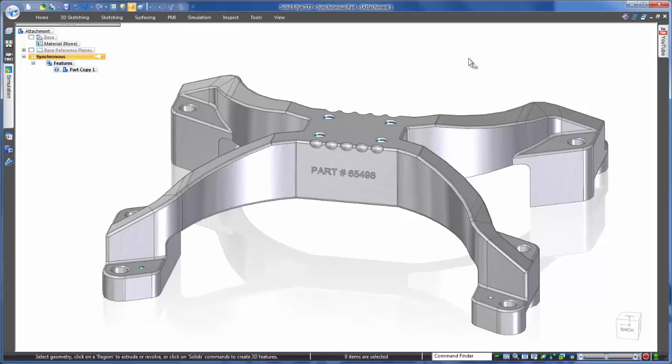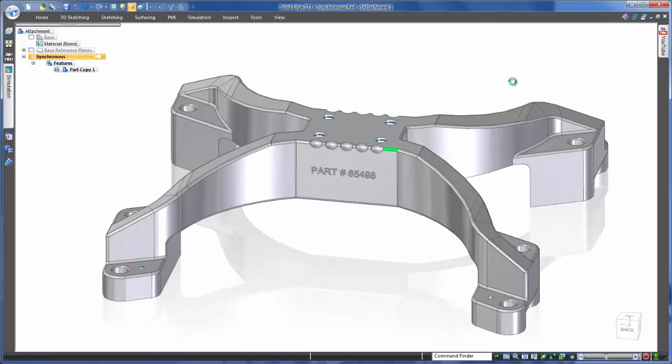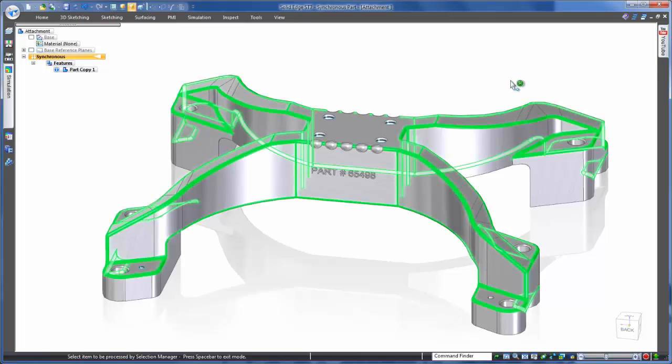Small faces can cause errors or long processing time, so it's always a good idea to remove these types of geometries if they don't greatly affect the structure. Unlike most other CAD systems, Solid Edge with Synchronous Technology doesn't rely on a delicate history tree, so removing features here won't cause rebuild issues. Most importantly though, it's just very easy.